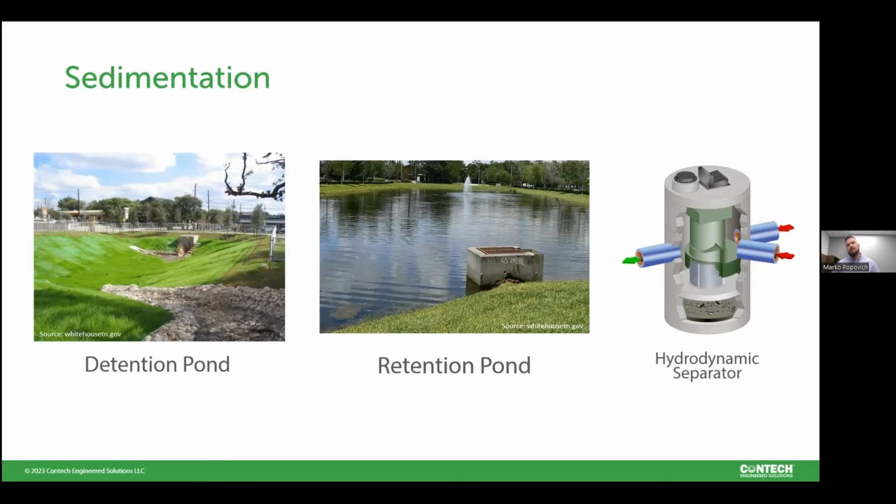Then you talk about it might not fully replace the pond, but if you can replace that forebay and get some sort of sedimentation within the separator, it does make maintenance a lot easier. These units, these ponds, everything has maintenance associated with it. If we're constantly capturing all the sediment that's coming in through the influent and we don't actually remove it from the structure that's capturing it, ultimately it will resuspend and discharge.